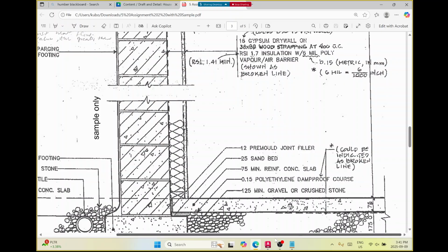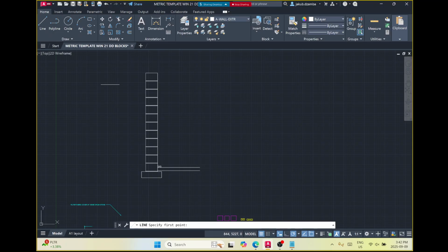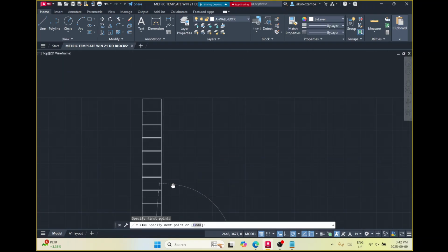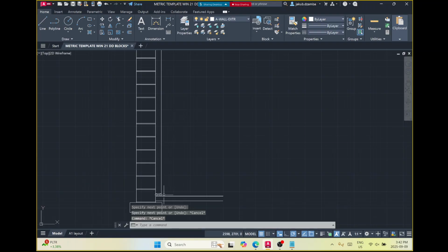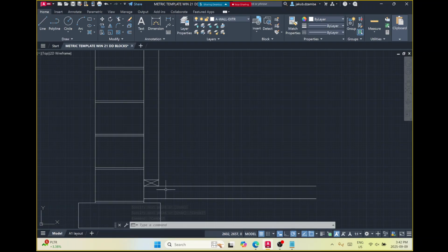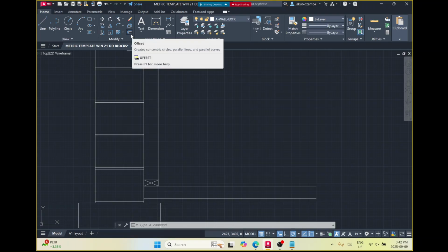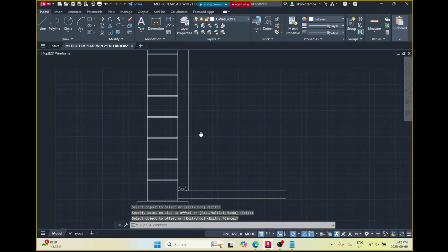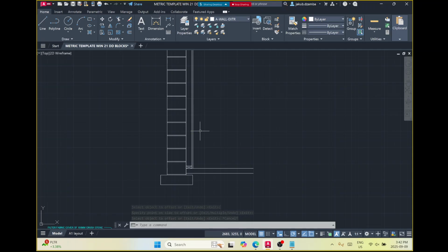That's 16 millimeters. So I'm going to click a line, start it at the outside corner of that rectangle, and just go in line with our top block and click there. And once I have that, I'm going to use the offset button, type in 16, and offset this out. And we're going to do one more line after that, and we're done for today. Offset was